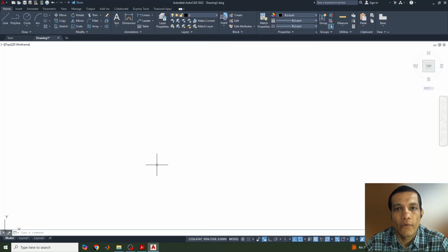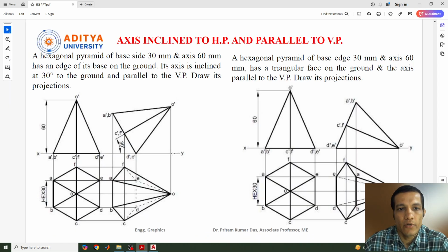Hi everyone, welcome to this new video lecture of AutoCAD. In this lecture, we'll discuss the projection of solids when the axis is inclined to HP and parallel to the vertical plane. So the question given here: a hexagonal pyramid of base side 30 mm, axis 60 mm,